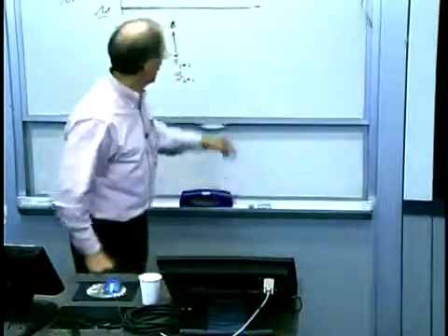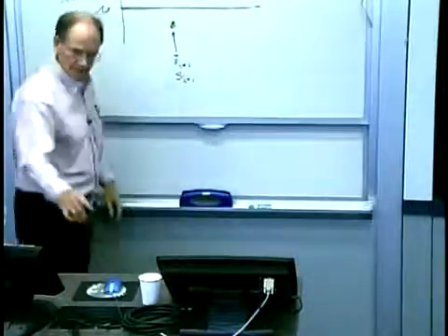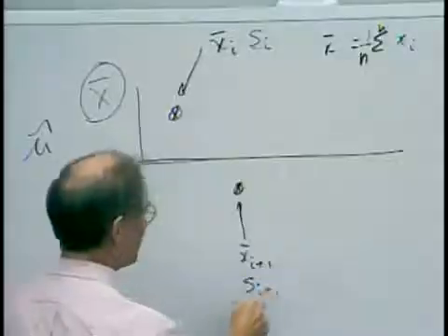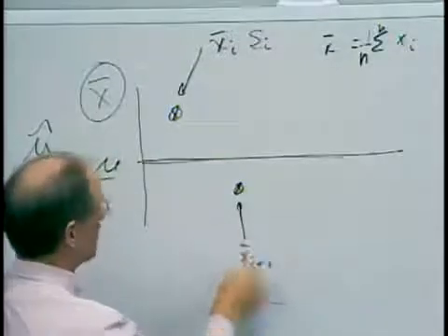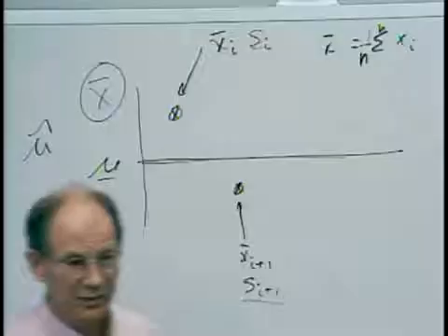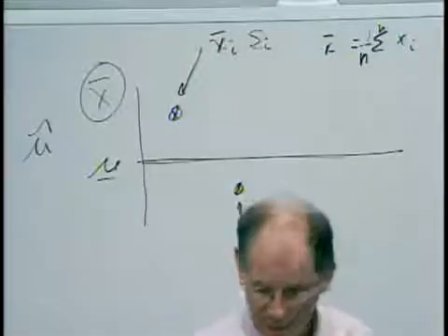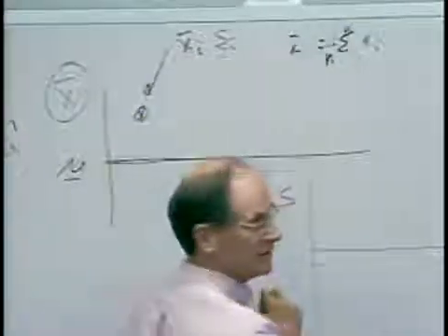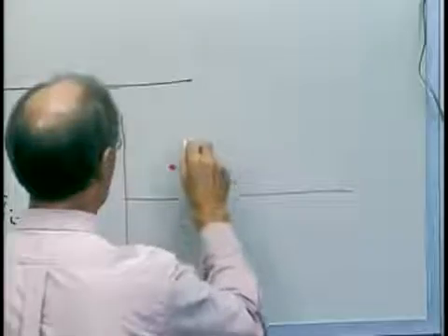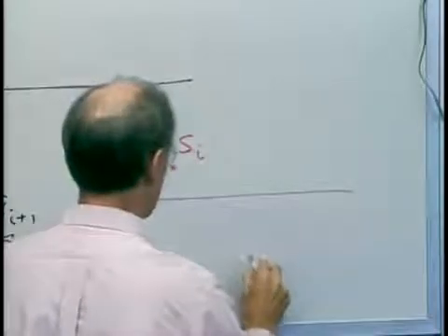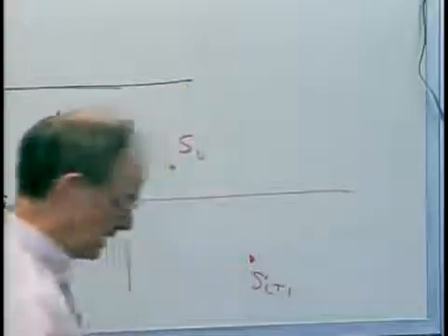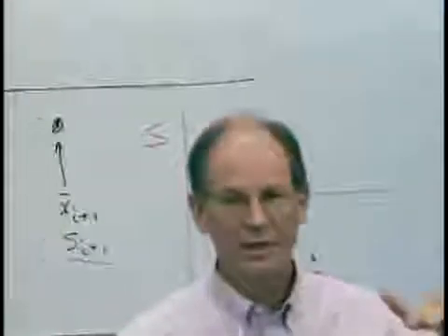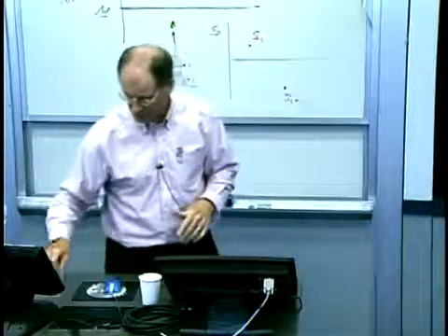Okay. Now, with respect to this S chart, since I can calculate these at each interval, you might say I could have a second chart where I could be plotting sequentially the standard deviation. Okay? So I can plot my sample standard deviation, and I could have another data point here and another data point here. And so I'm actually looking at both. I'm plotting the sample statistics for the mean and the sample statistics for the standard deviation.